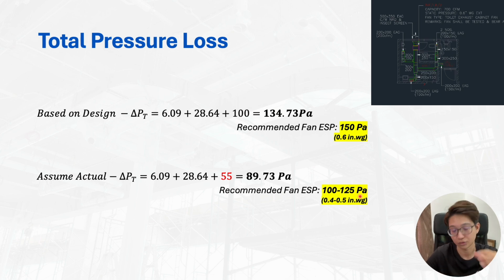So to give you a sense of the costing difference, the higher the static pressure, the more expensive the fan gets. So this is how you calculate duct static pressure. Not very hard if you have an Excel sheet to help you with the Darcy equation. The fitting loss is lengthy, but if we can calculate it instead of estimating, then we know actually how the system will perform.